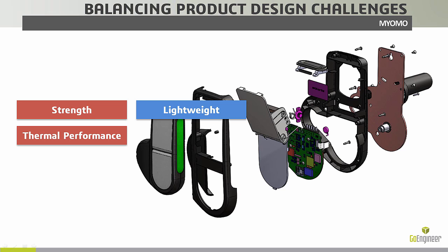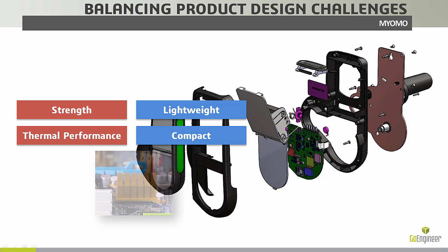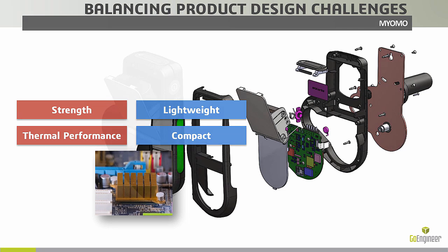Now, thermal performance. Can we heat sink the part without compromising its compactness? As far as thermal performance goes, you need enough airflow within the component to carry the heat away from whatever heat sinking methodology that you figured out. Now, this is only scratching the surface with all the problems that this component might undergo during its performance. So we need to be able to predict all these problems beforehand, and that's when simulation comes in handy.